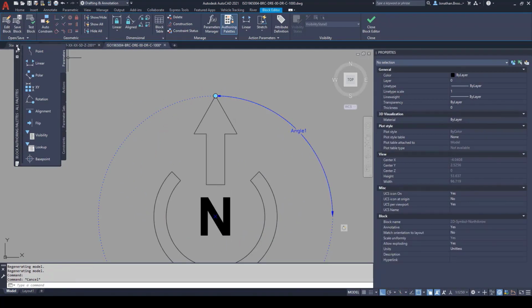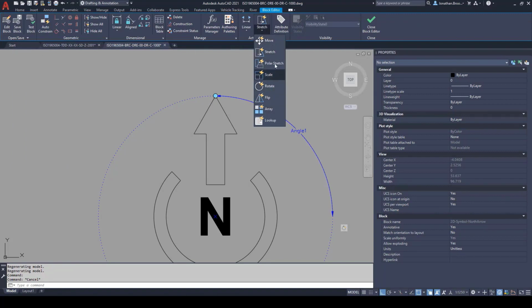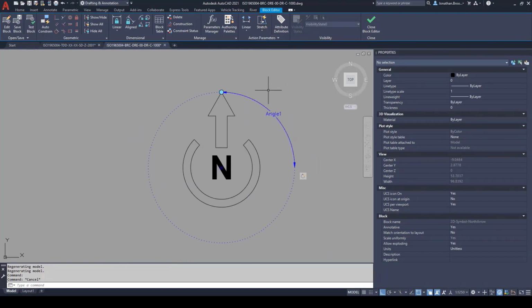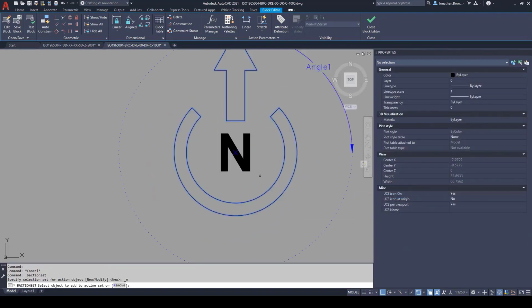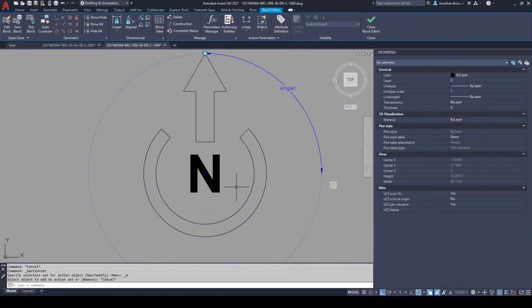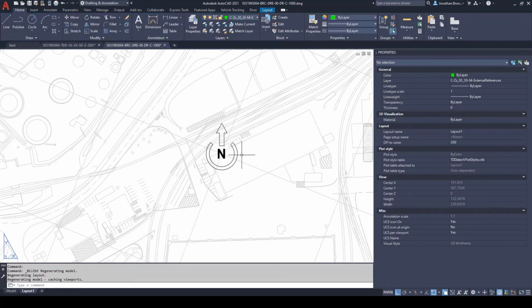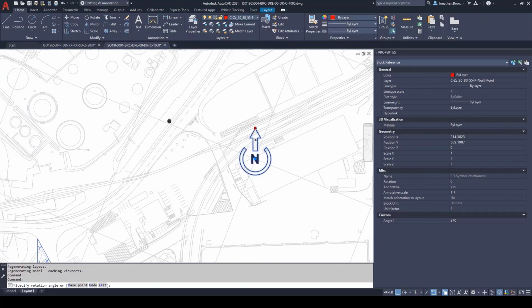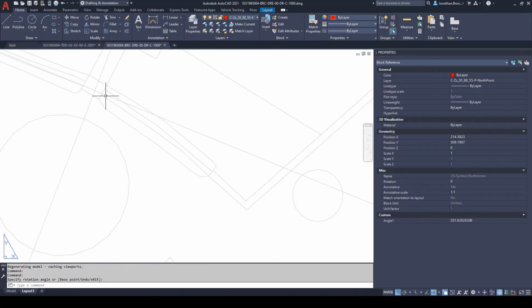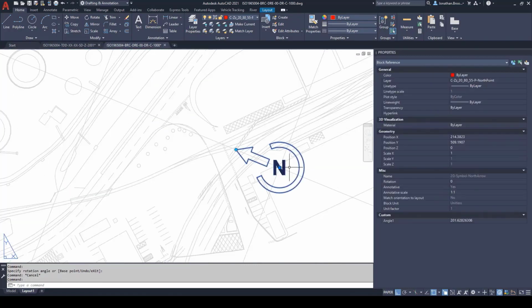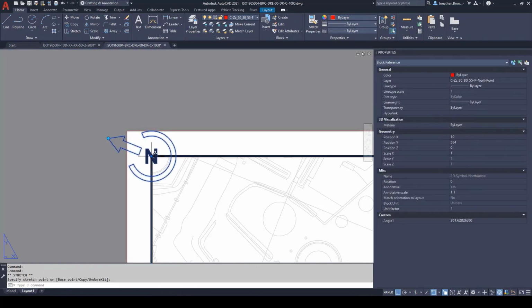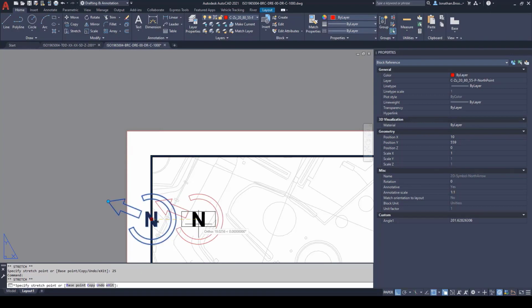By using a reference point, users can stipulate which items inside of an AutoCAD block they wish to rotate using the parameter. It could have various uses, including the rotation of symbology such as section marks and north arrows, or it could be used for components such as the rotation of a construction crane or excavator model block. Rotation parameters allow the different instances of the same block type to have various rotational outcomes depending on the user requirements inside of AutoCAD.